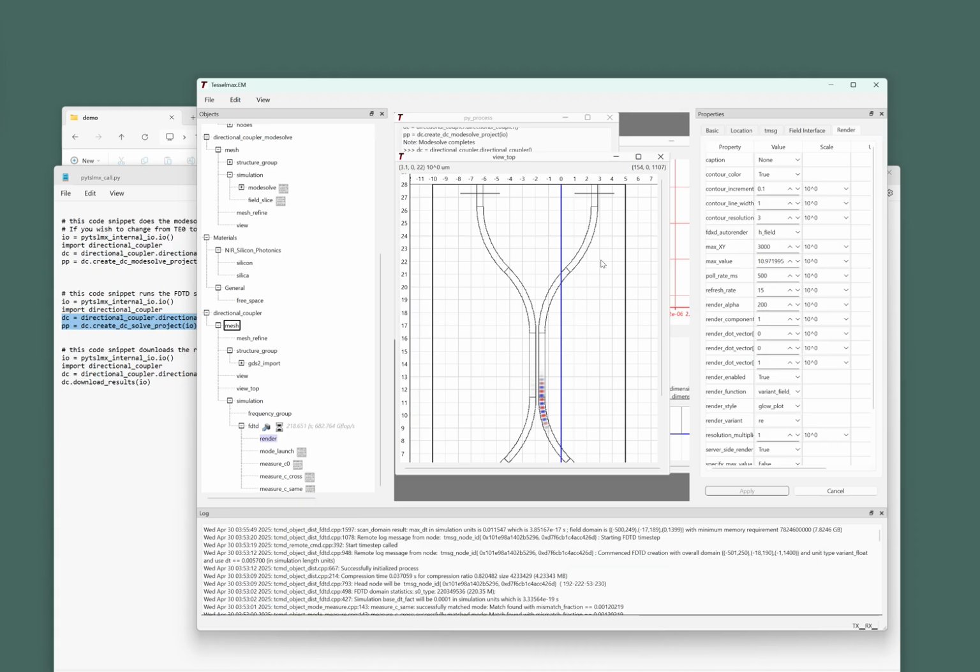So actually the full capacity of this machine is 640 gigabytes for FDTD domains. And yeah, you probably couldn't use exactly 640. You can get close, 500, 550. So this is a little bit over, somewhere between 1 or 2% of the full memory capacity of this machine. So it's not a surprise it's not scaling all that well, but it's not terrible. And for this simulation, it'll be done quite soon.